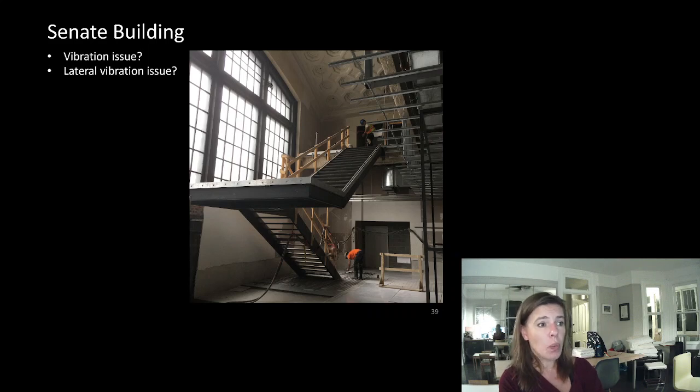One thing we determined is that they hadn't fully welded all of these in yet. So those needed to be welded in to help prevent it wanting to rack. Once that went in, the overall deflection panic stopped. But now they were aware of it. And once somebody's aware of it, you can't be unaware of it. It's like a song that you hear. You're fine never thinking about it, but once you hear it, it's stuck in your head.